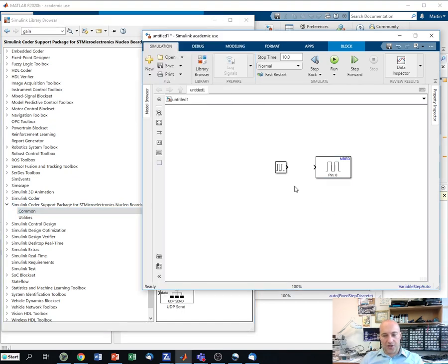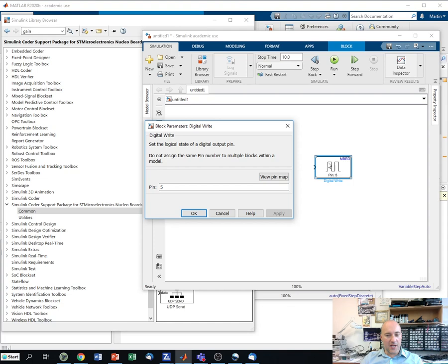Now let's finish this block diagram. We just need to configure this pin correctly so that it is connected to the LED. For the first example, I will just use one LED on the board. I will use the red one as we've done 2 weeks ago. So this is the pin PB14, and you need to write it like this because this is a constant saying where it is actually connected.